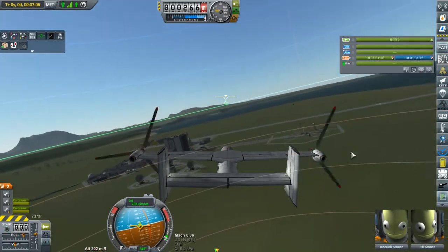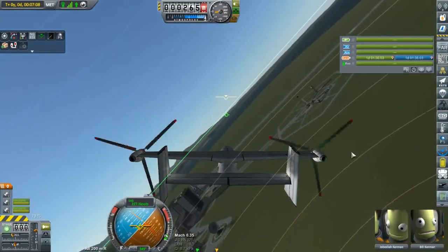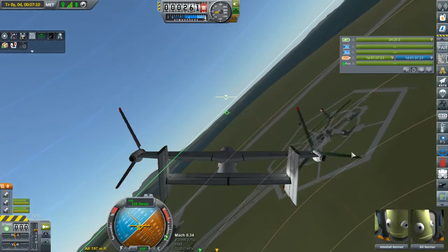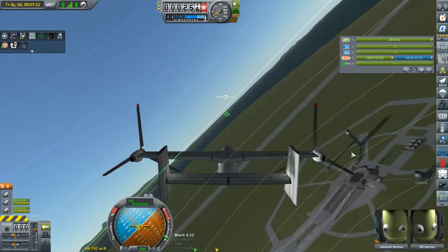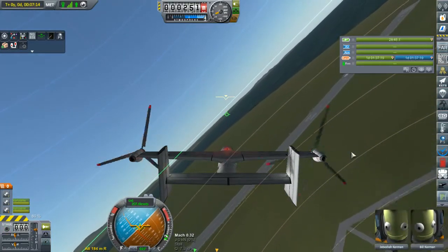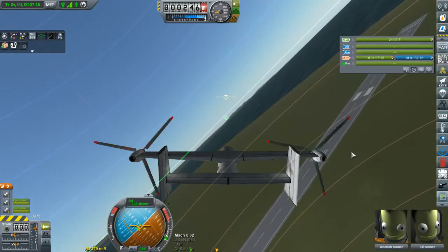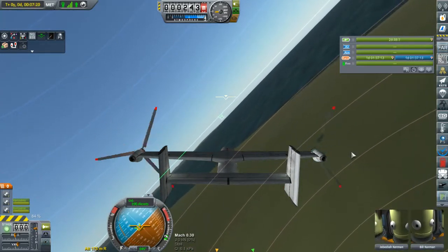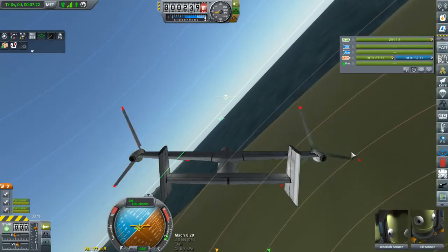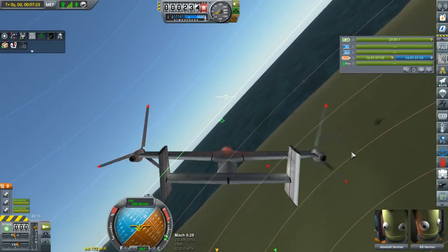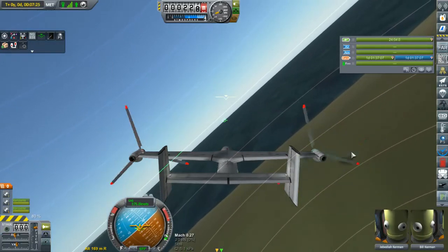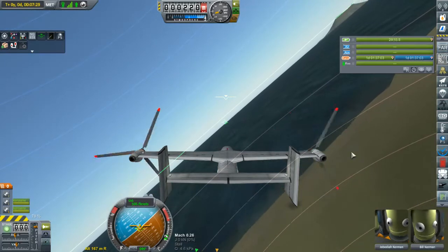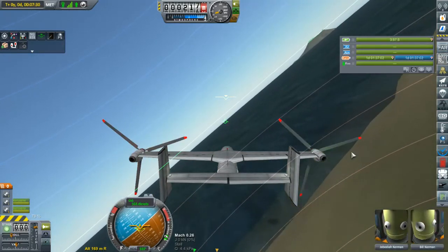So, for the moment, let's practice our next component of this flight. We're going to slow down. In this case, I've cut the throttle all the way back to 0 collective, so this thing is just going to kind of settle. We're going to keep that nose off the ground. As we slow down, I'm going to start bringing this thing back.